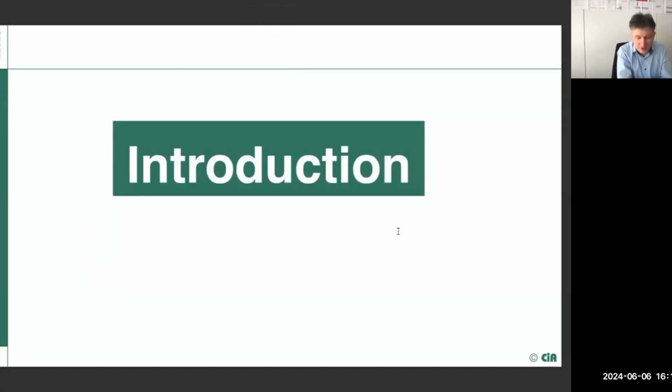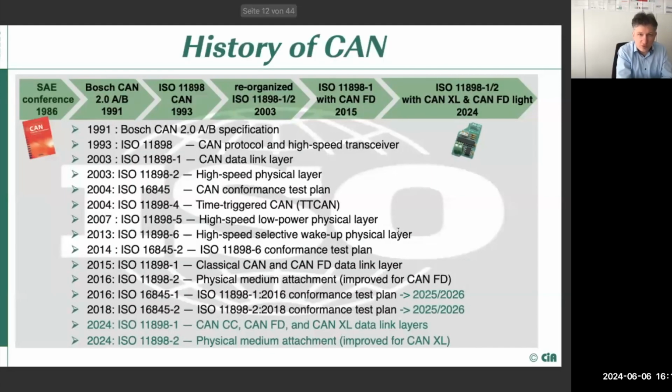So far about this general introduction to automation. Now I would do a short introduction into CAN XL. As I said, there are three technologies. If you are familiar with them, this is okay. We will talk about the third one, with the newest technology called CAN XL. It is extra large, allowing up to 2048 bytes, which is 48 bytes longer than an Ethernet frame, allowing Ethernet frames to tunnel through the CAN network. That is the biggest advantage so far.